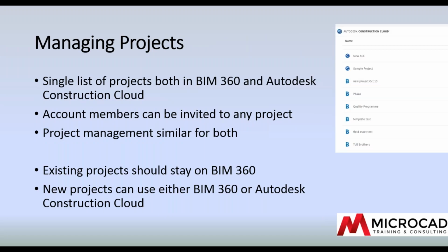As I said, the new products can work with either the BIM 360 or the Autodesk Construction Cloud. The account management module is a single place to see both kinds of projects for your account. You have all project management tools for either kind of project. If you have existing projects on the BIM 360 platform, we strongly recommend you stay on that platform. At this time, there's no migration tool from BIM 360 to the Autodesk Construction Cloud platforms.